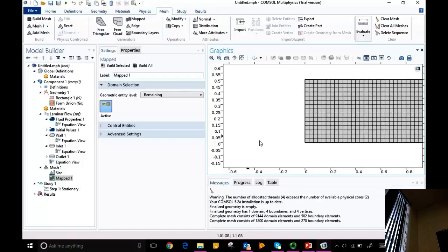But in triangular meshes, I don't have that. So I need to store a connectivity matrix in addition to the coordinate matrix. Okay? So there are 2 pieces of information that you store. But what is the advantage of a triangular mesh? If you have a complicated geometry, try fitting it with this rectangular mesh. It's not possible. Triangular mesh, you can always squeeze it in. Okay, so by default, they have.